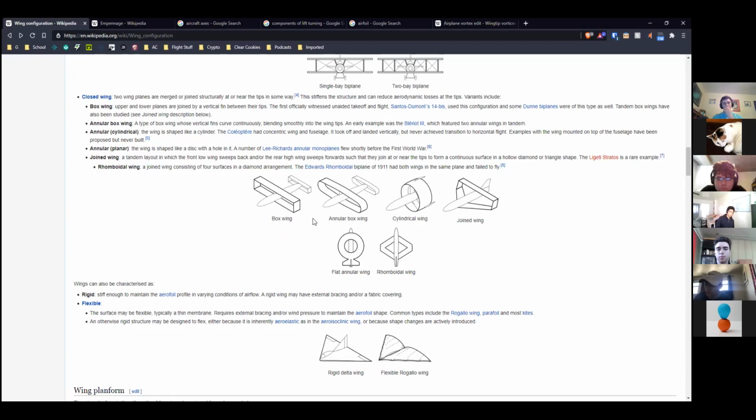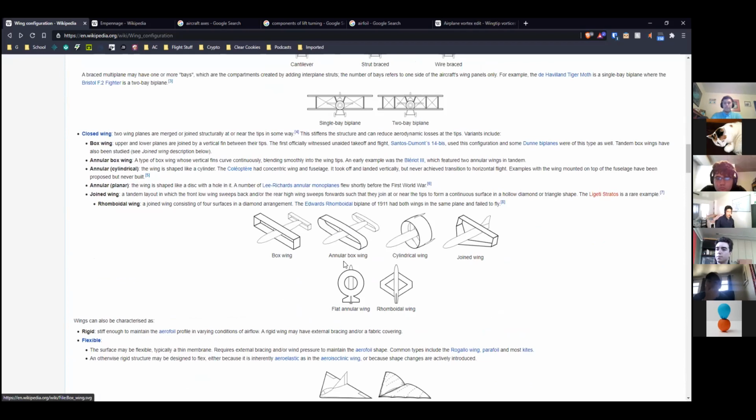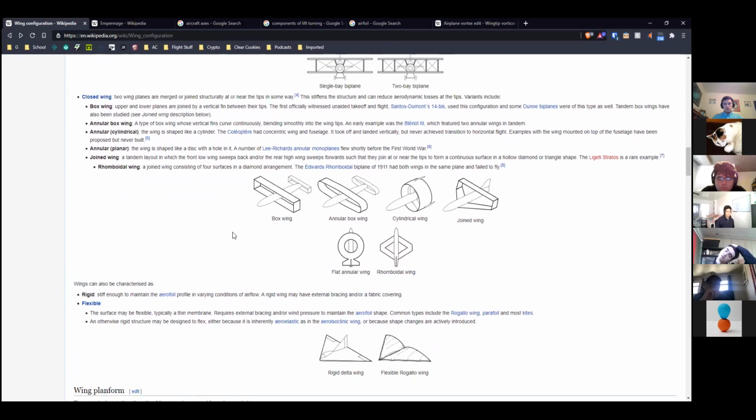So even though it wants to, air quotes, it won't form as strong of a vortex, and so the efficiency of your wing will be higher. So these are different ways of closing off the wing, which is under support because that means the wing can self-support more if there are two of them. But it also will help with your performance.